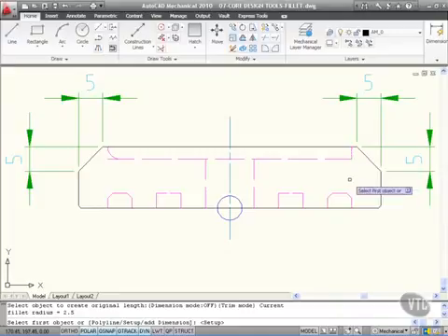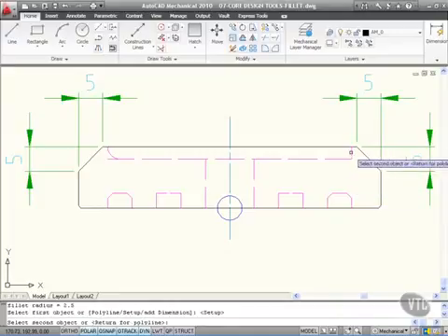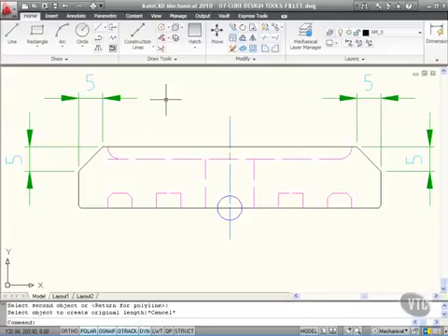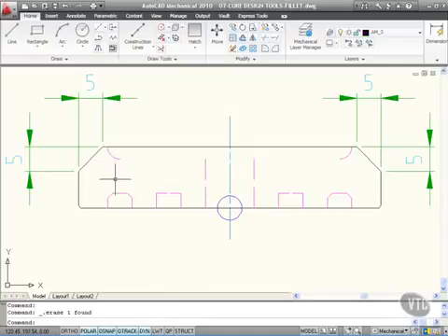Now, it didn't work that time. Let's just click again. 1, 2. Obviously didn't click correctly. But you'll notice again, look, I've got a line there that shouldn't be there. So what I'll do is I'll press escape, remember, to come out, like with chamfer. Click on that line there, and if I hit delete now, what happens? That line completely disappears. I'm just going to undo that.